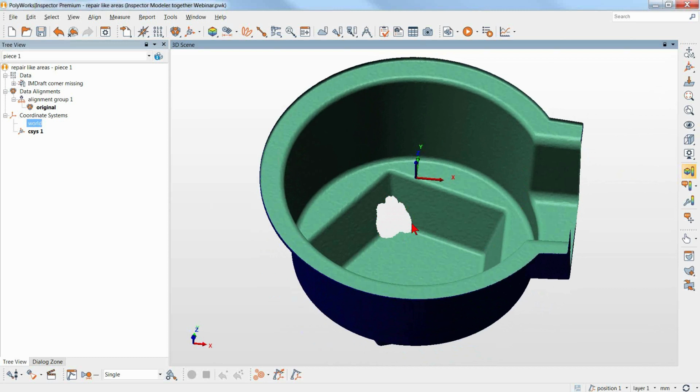It can be a matter of there being no material there. It's actually very shiny, where we have some grease or something that's giving us no feedback. Or it could be simply that the sensor that you're using to scan is too big and you just can't quite get the angle to get down inside.